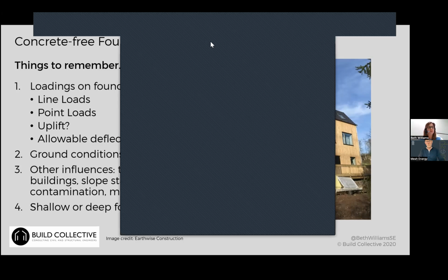Often the cost is the limiting factor. If you're looking at something that isn't the really domestic shed type of screw piles, they can get quite expensive, particularly compared to other types of piling. We've had a couple of projects recently where the site needed to be piled anyway, and they said, oh great, we'll use screw piles. But then they were double the cost of a concrete pile. So both projects ended up going for a concrete pile of various different types. So that was a big consideration.